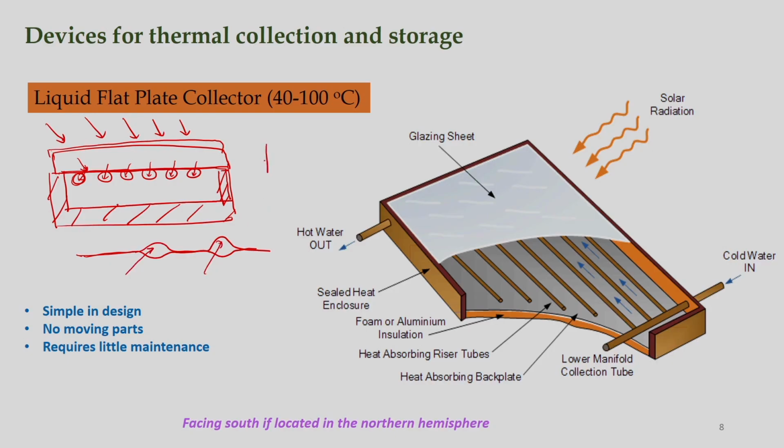these fluids are stored in an insulated vessel, and this can be used as per required time. So, here what happens, solar radiation is falling through this glass cover and received by the absorber plate, and then heat has to be transferred to this working fluid. Finally, this fluid is used for different applications, like maybe taking bath, or maybe doing different activities, and these are the insulations, so that heat transfer can be reduced. So, this is the very basic liquid flat plate collector.